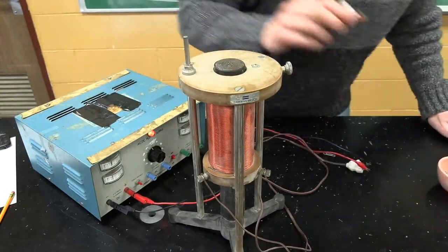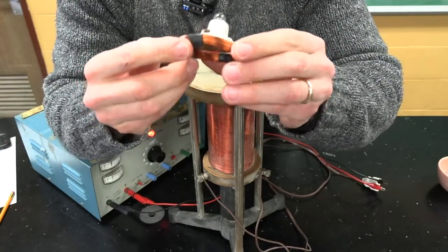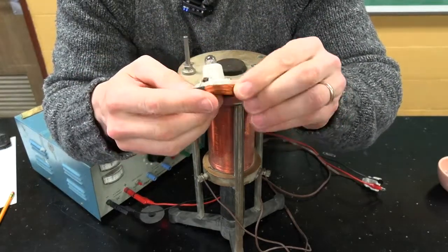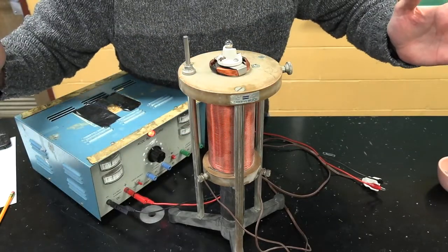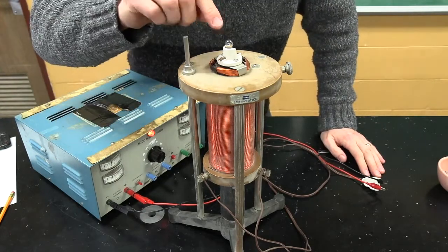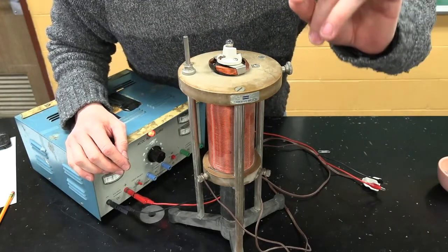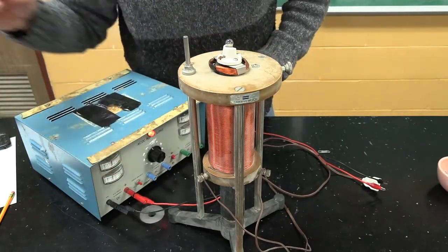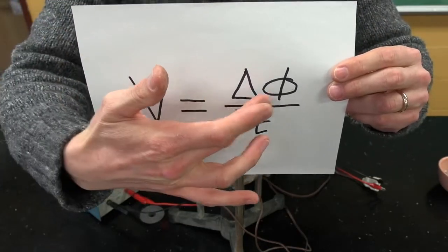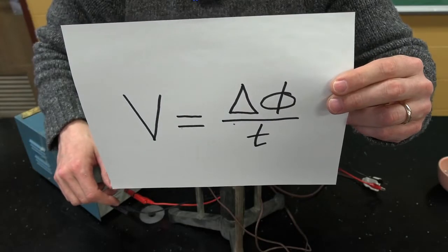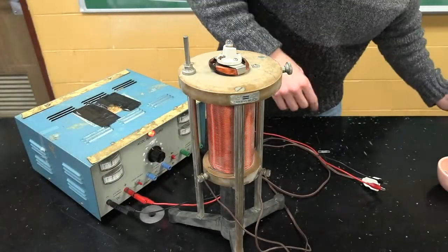Now what I'm going to do is I'm going to take this light bulb, which is connected to a coil of wire, only spiraling around, not connected to any battery source, and I'm going to put it on here, and we're going to see no light. And you should know why. Why didn't that light come on? We have magnetic flux going through the coil. Why no voltage? Why no electricity? Well, hopefully you said, I know why, because we had flux, but it wasn't changing. So no changing flux, no voltage, no current, light doesn't come on.